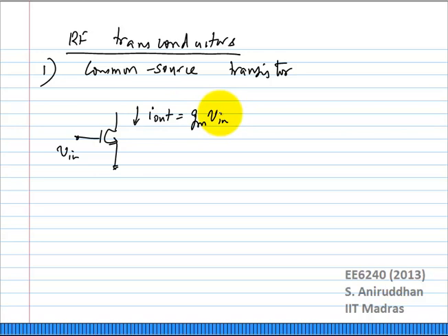How do you control the linearity? Now note that in the case of the mixer, we are going to approach things slightly differently. In the case of the LNA, noise was paramount, right? So we did all the noise analysis up front, right? And then we went to linearity and said, okay, your noise is most important. You are going to design your circuit for noise. Linearity will take a little bit of a backseat. It's important, but it's of less importance than the noise.